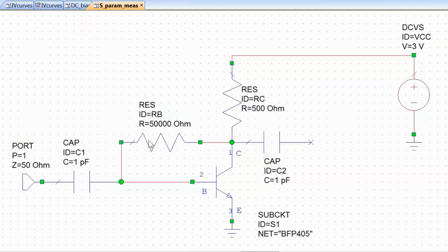So now when I get a DC current here, the current won't be able to go through the capacitor, which is an open circuit at DC, and hence the bias network won't be loaded by the 50 ohm internal resistance of my RF source. Similarly, when I put an output test port on this other side, because the capacitor is an open circuit at DC, the 50 ohm impedance of this port won't be able to load my DC bias circuit either. But what value of capacitor should I choose? This is quite an important issue.